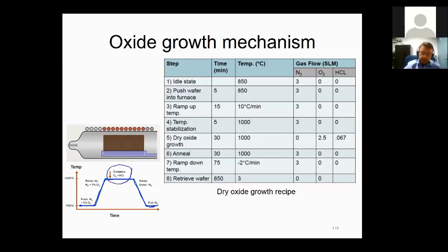If you do not wait for the cool down or the ramp up, first you can harm the tool because it can't catch up with the speed. Secondly, and maybe more importantly, you can build up a lot of thermal stress on your wafer. So all these wafers, once they are taken out from, let's say, 1,000 degrees to outside room temperature, 25 degrees, there's going to be too much of a sudden abrupt change in temperature, and it may build up unequal amounts of stress on certain points, and it may just break the whole wafer.